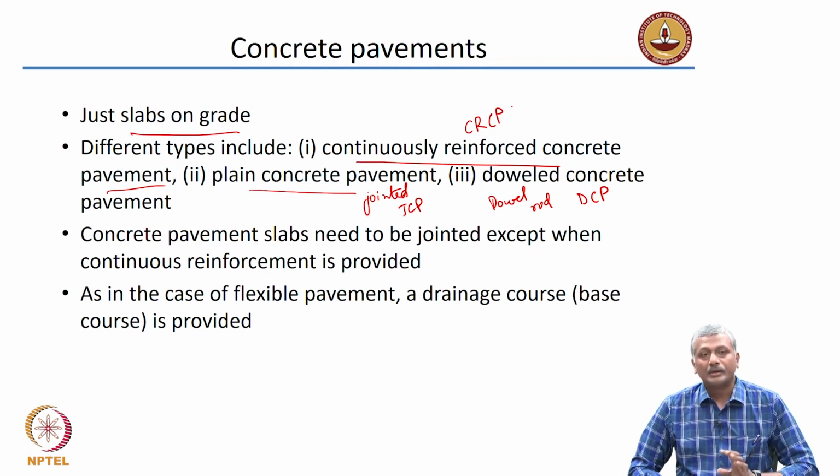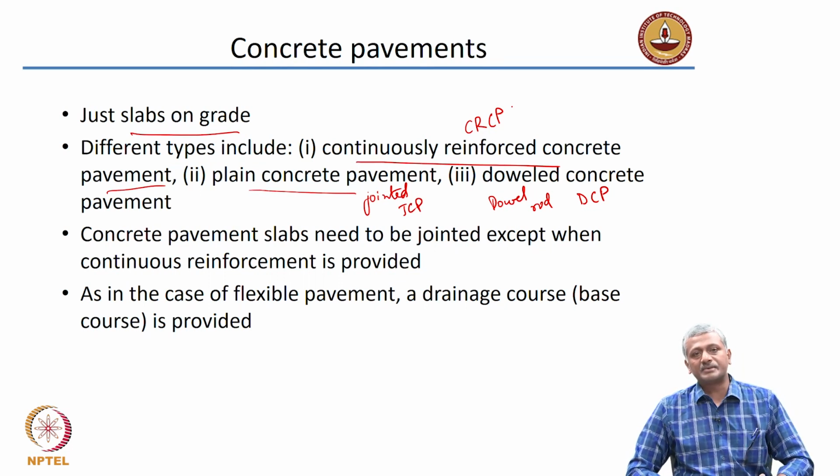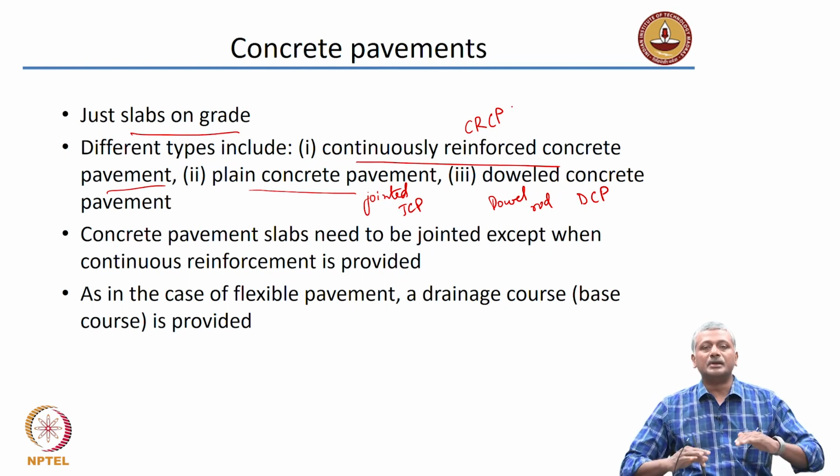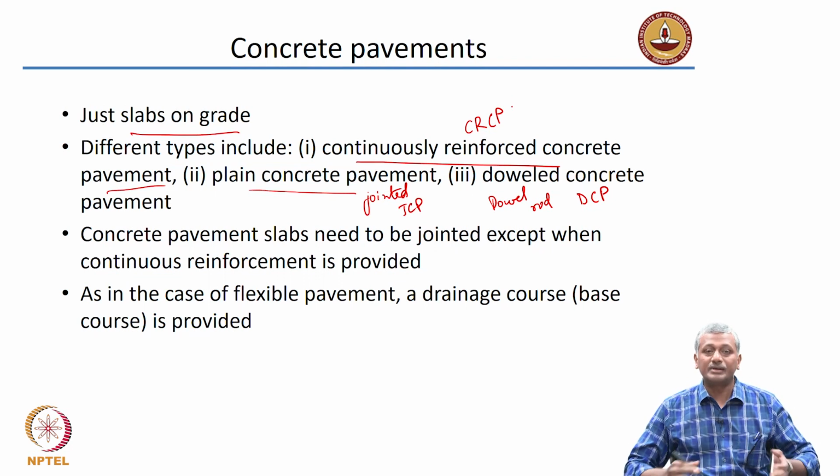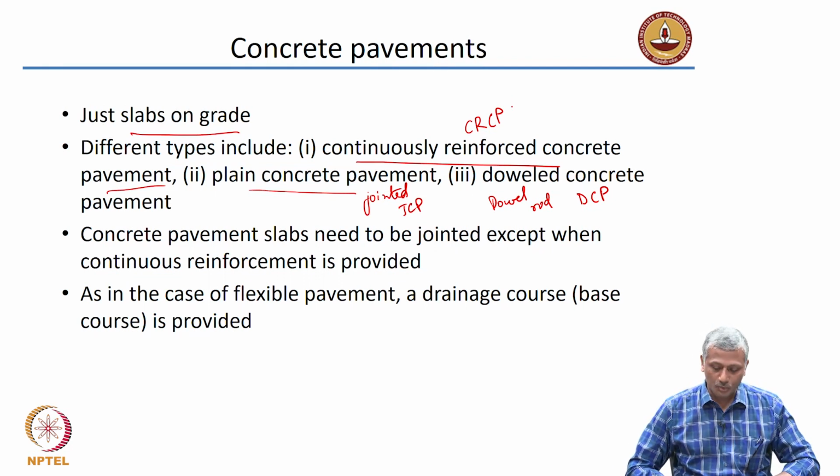Now, just similar to the case of the flexible pavement, you need to provide a base course which is meant not just for stability of the pavement but also for drainage. Okay, you need to provide that drainage course.